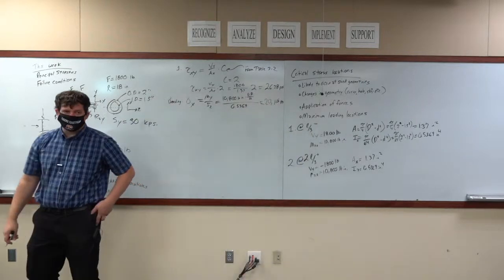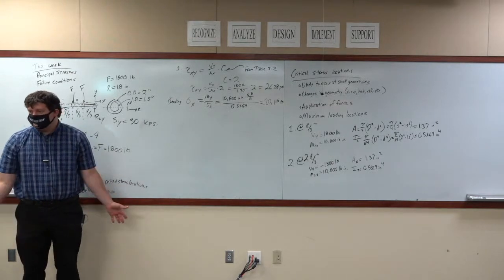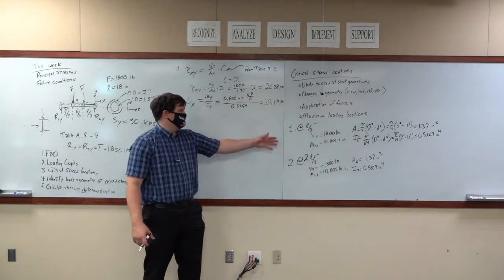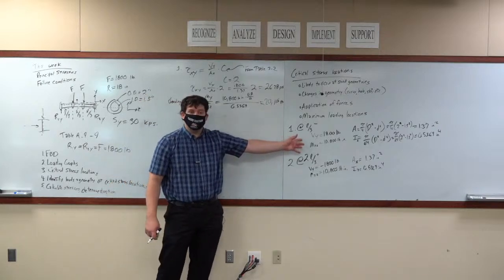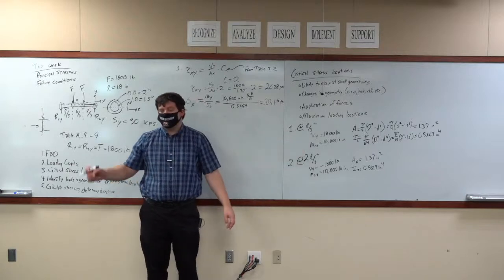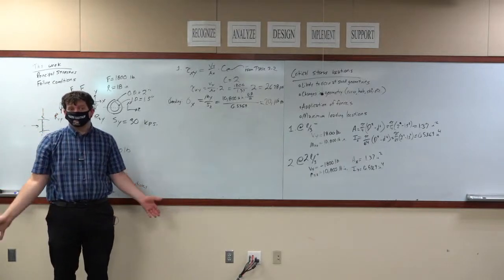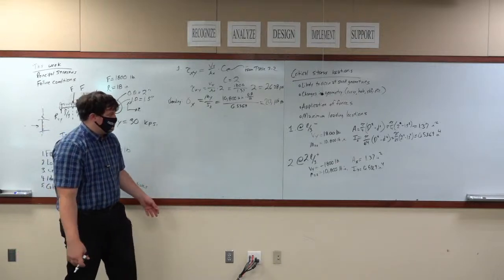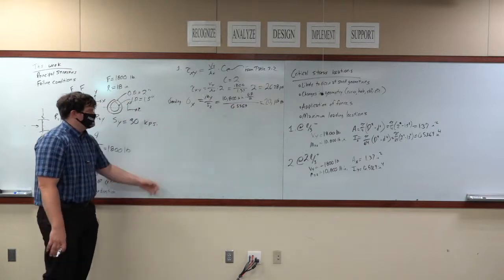Do we have any other stresses on this element? Well, we do, but they're small enough we're ignoring them. There is actually shear stress created by bending, and there is also normal stress created by shear force, et cetera, et cetera. But we're only going to calculate one stress per loading condition because we're calculating the most important stress. The other stresses are small enough, they're dwarfed. It is almost as if they don't even matter. So we're ignoring them, okay? One stress per loading condition. We only had 2 loading conditions. We're good. This is all we need.